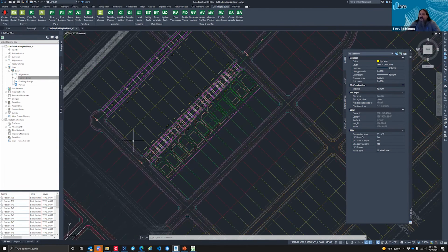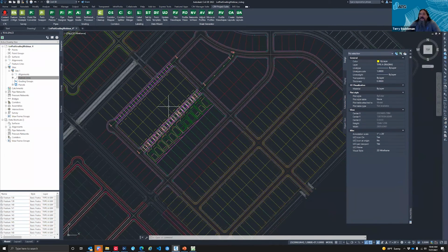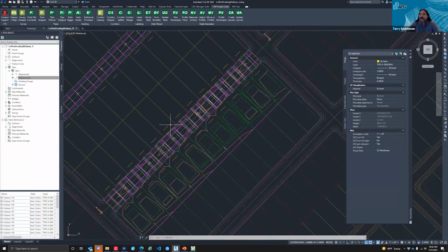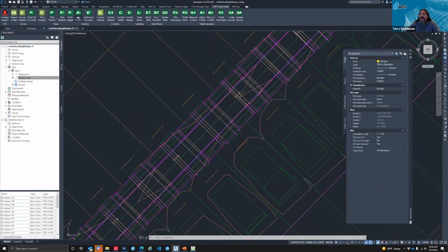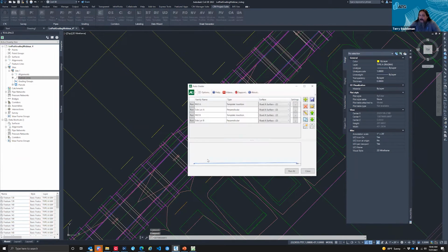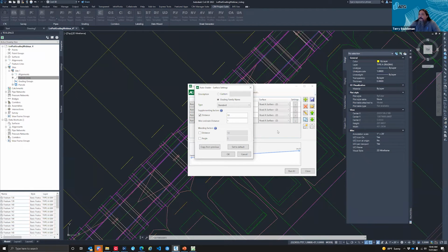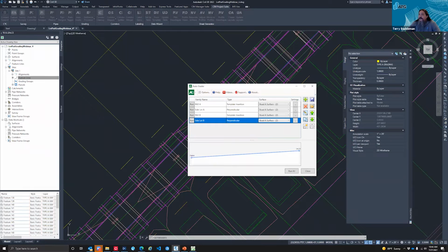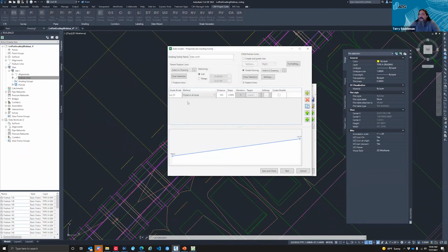So with that, we can go through and look at our other grading families as well. We have a couple created, and then we'll go and look at labeling our lots. So again, we have this type B here, and this one is basically using, sorry, some little factors, we'll edit our side B. It's basically using a flat 2% slope to go from the parent to the back lot. In this drawing, we have 0 features selected, and we have 1 feature line object.